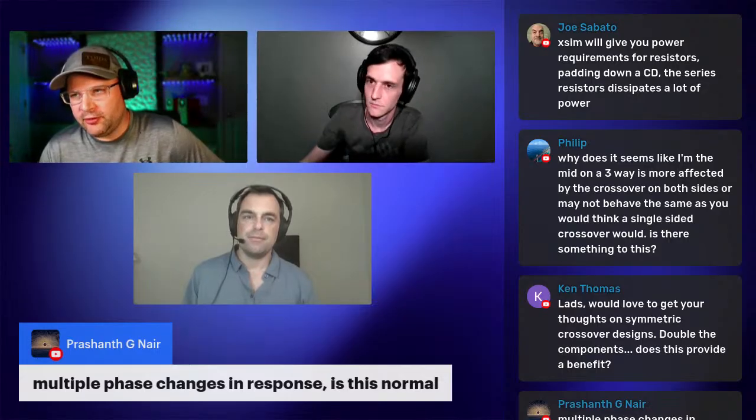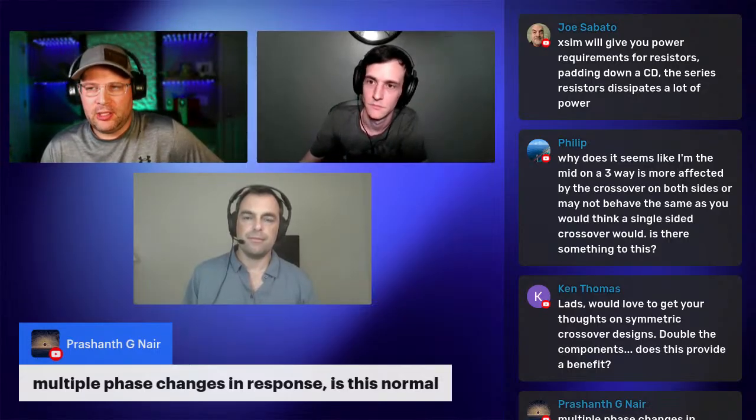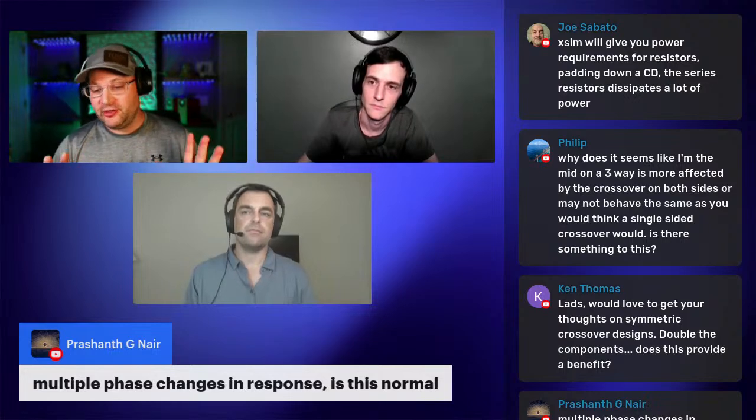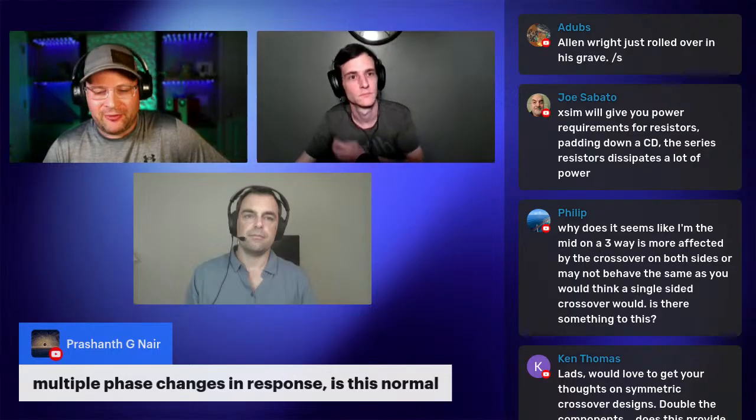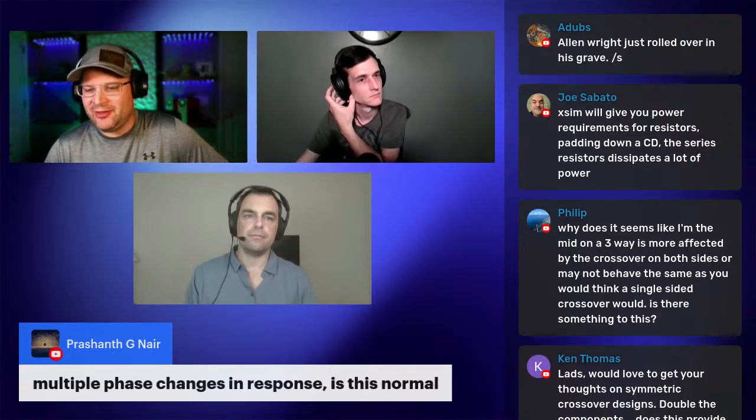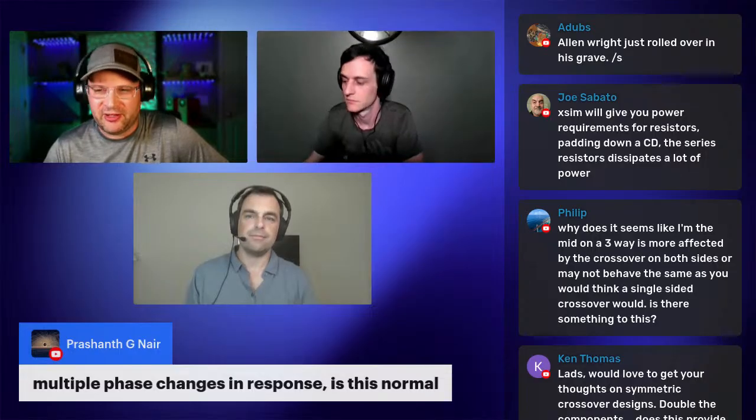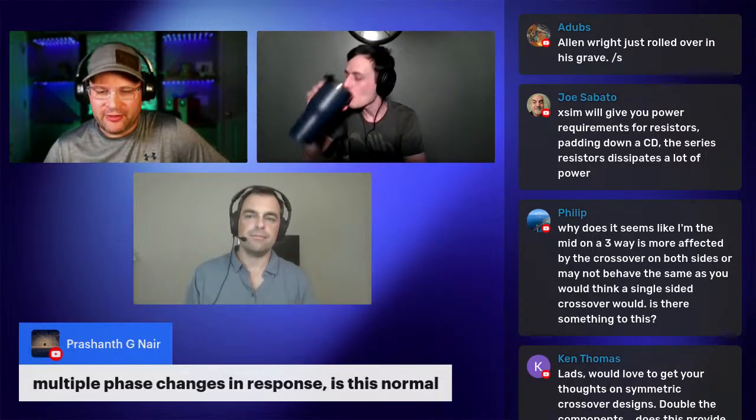So I will say this too. When you're designing a crossover, don't just go off your simulated response. I see that way too often. People will take the simulated response, look at it. Well, not only double check, but also listen to it. I know I've created, for example, some notch filters that looked beautiful on their response. I'm like, this is gorgeous. And then I listened to it with and without it, and I was like, you know what? I actually like it better without it. That happens sometimes where, believe it or not, it might look better, might even measure better, but when you listen to it, you're like, nah, there's something else going on here. So just think about that as well.